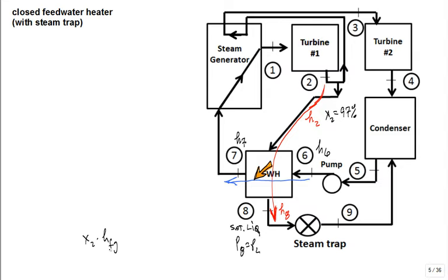Let's say it comes in at, I don't know, some 97%. Well, 3% is already condensed, and I need to condense the 97%. And so that occurring at constant pressure allows us to calculate how much heat comes out of that fluid stream.